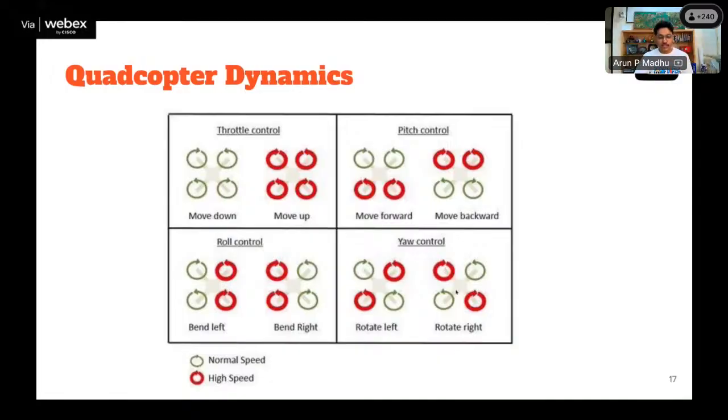Have you noticed anything in all of this diagram and the previous diagram? Have you wondered that the motors do not rotate in any random direction? They have to rotate in a set direction. One motor can't randomly rotate clockwise and another randomly anti-clockwise. There is a set pattern of rotation for the motors so the drone will be able to fly, which is, in a quadcopter, always make sure the diagonally opposite motors are rotating in the same direction.